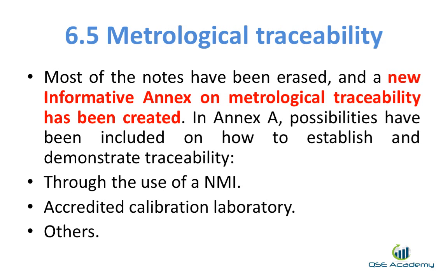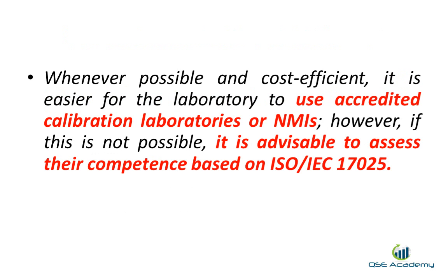6.5. Metrological traceability. Most of the notes have been erased, and a new informative annex on metrological traceability has been created. In Annex A, possibilities have been included on how to establish and demonstrate traceability through the use of a NMI, accredited calibration laboratory, others. Whenever possible and cost efficient, it is easier for the laboratory to use accredited calibration laboratories or NMIs. However, if this is not possible, it is advisable to assess their competence based on ISO IEC 17025.